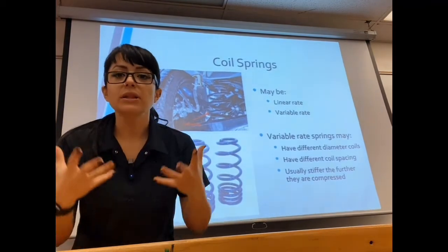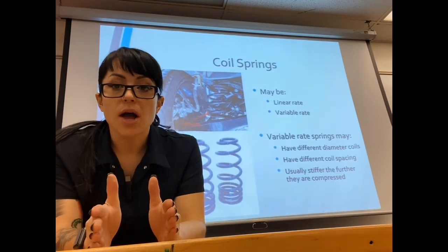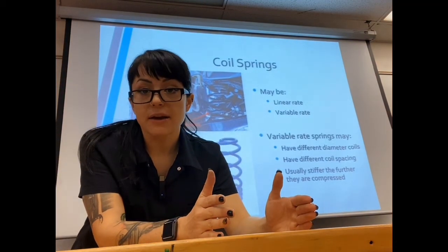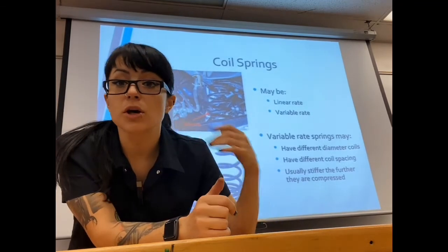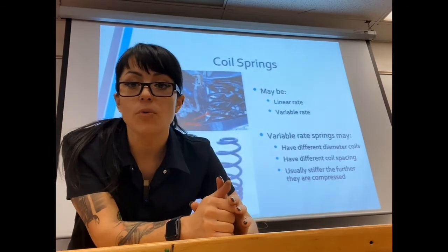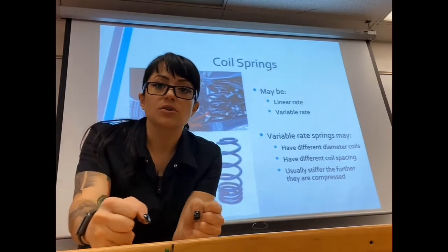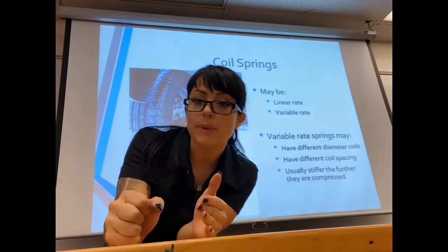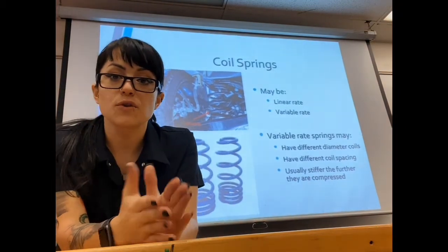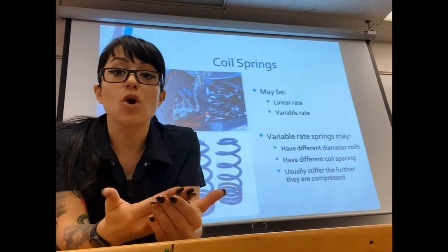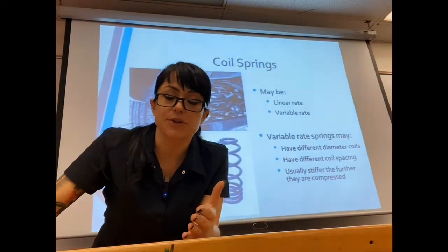So usually you want a variable rate spring when you want a nice comfortable ride on daily driving, but let's say you want to start taking corners really rough, or you want to start loading up your vehicle so it can carry more weight. Usually it's a handling thing. When you start to take turns a little bit harder, you're going to get a little bit more weight transfer, so you're going to compress that spring even further. So when you get that weight transfer, the spring tends to stiffen up so you don't get near as much body lean or that weight transferring to your outside.